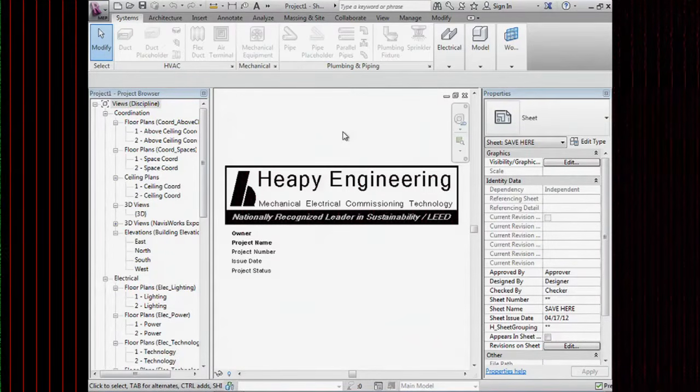So the question is, can you incorporate noise criteria into your ductwork sizing? In summary, the only way you're going to get around that is through experience. I've worked with a couple of acoustical consultants. You have certain areas where they basically say nothing more than 750 feet per minute or whatever. You can set that to size that particular system at 750 feet per minute, but that's probably the best you're going to be able to do. It's a manual override, and we'll talk about that when we get into the duct and pipe tools.